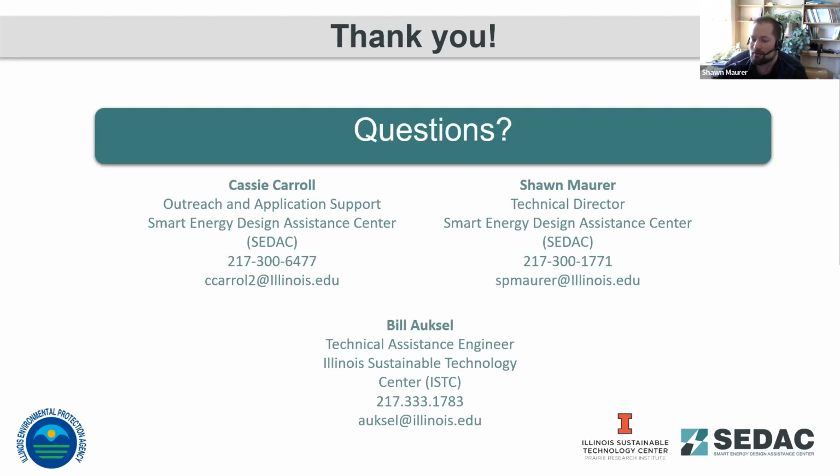We've also seen there's optimization programs built into VFDs now, where instead of trying to maintain a constant level in a wet well, maybe it's more efficient to draw it down at a constant rate, or it depends on the system and what you're looking at. So there's different efficiency opportunities there, and it depends on what's installed. And there are pumps and VFDs that will monitor their operating speed and do that adjustment by themselves. So they are kind of self-checking to make sure they're at the most efficient speed, and they will slow down or ramp up to adjust that themselves. Yep.